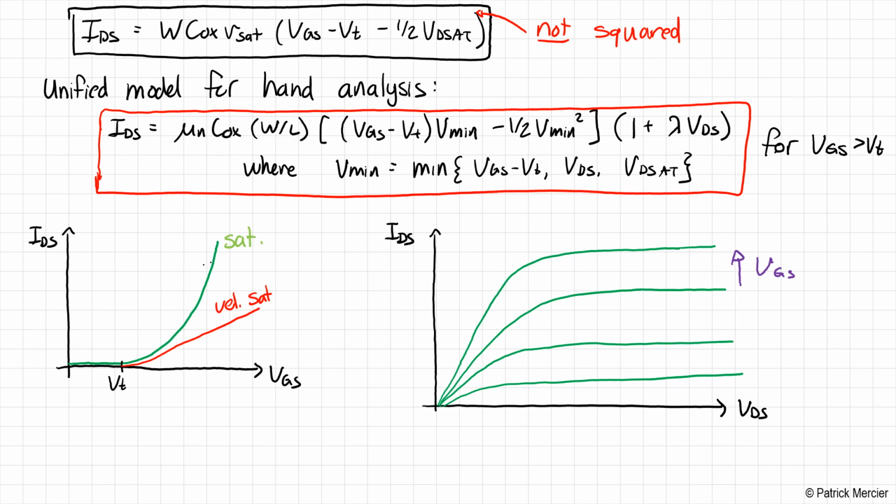But if you go ahead and plug the results into this formula, you'll find that VGS minus VT could still be positive and obviously in the above threshold regime, but VGS minus VT could be smaller than VDsat, which implies that we could still be in the saturation regime even for very large values of VDS per that formula.